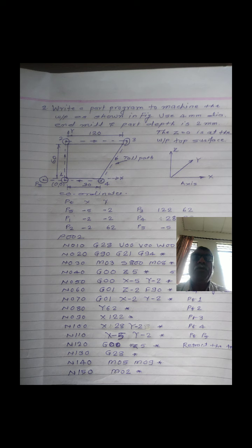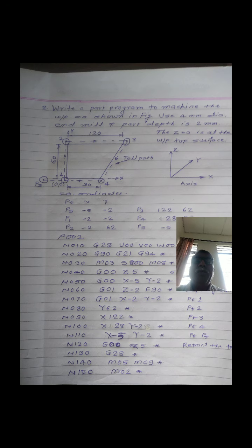Use a 4 mm diameter end mill cutter and part depth is 2 mm. The Z equal to 0 is at the top surface of the workpiece.